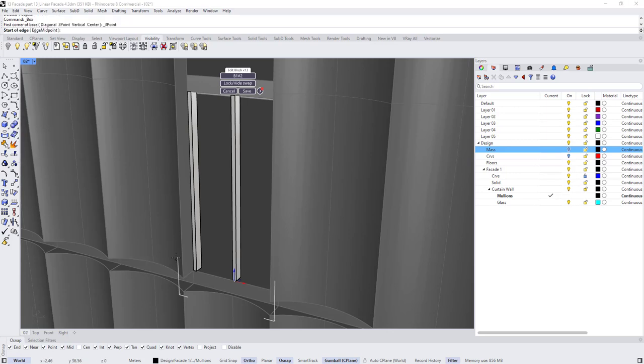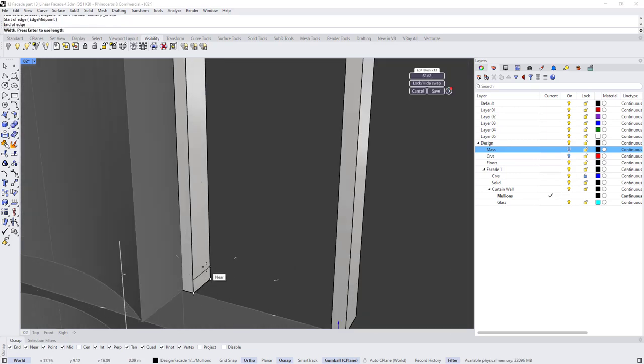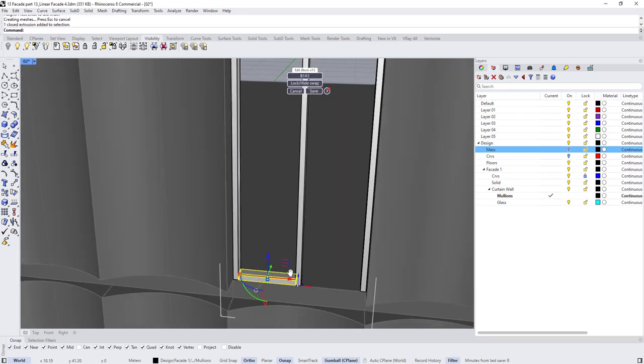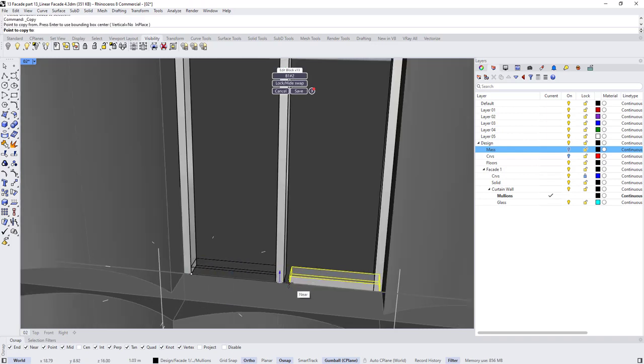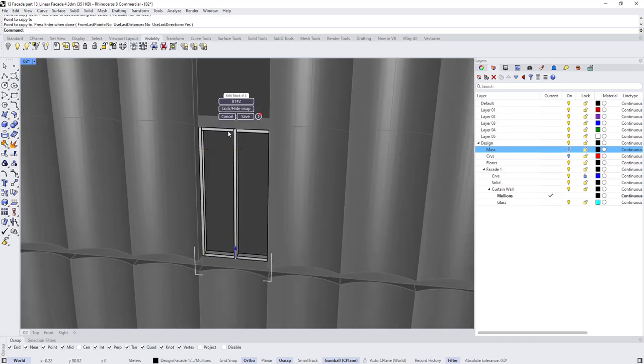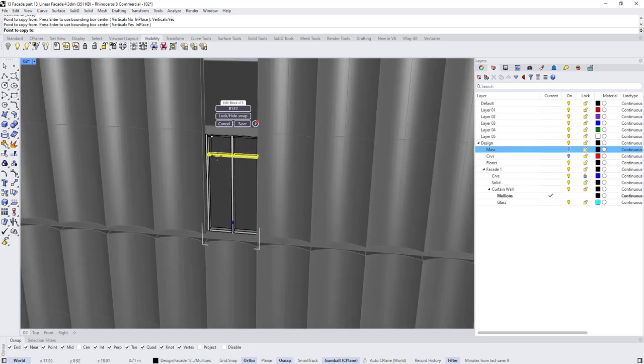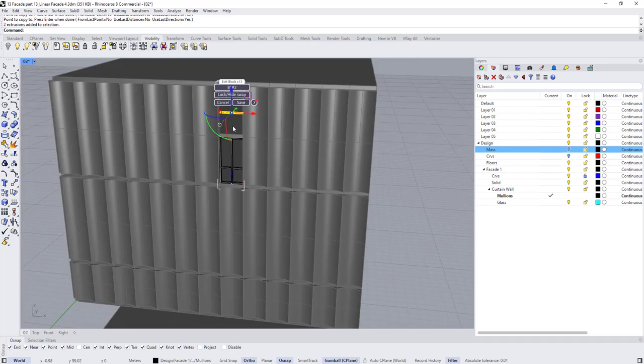Let's choose 3-point box. Let's create one from here to here. Let's set the height 0.05, maybe 0.082, something like this. Copy it, this. Select both of them, hold shift, select both of them, copy vertical from here, this one, copy vertical, and move it down by a value of maybe 2.4, negative 2.4, something like this, this one.